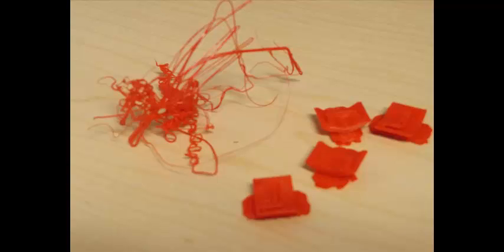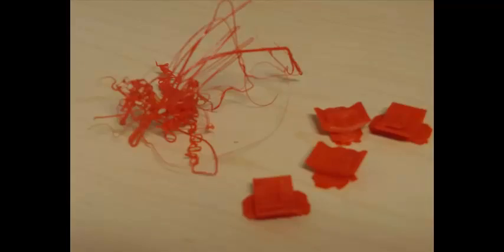As you can see, once the printer reaches a certain point on the model, it loses its base to print upon. This happens when the wheels meet the body and the printer has no support to print the body on. Now that we know this, we can go back to SOLIDWORKS and make some changes. We will need to modify settings within the Makerbot software to add supports while printing.